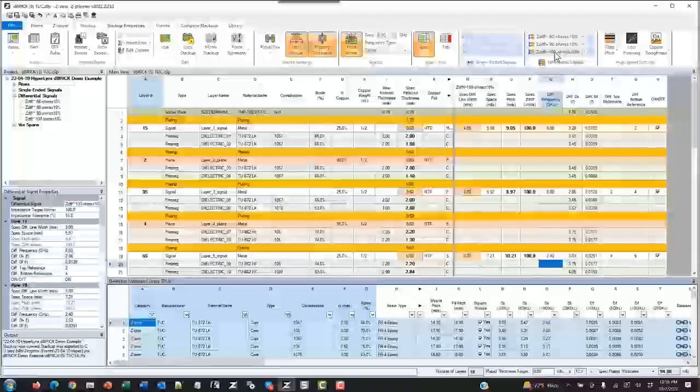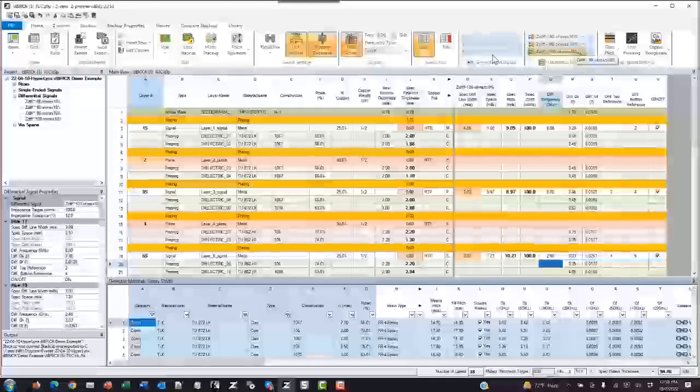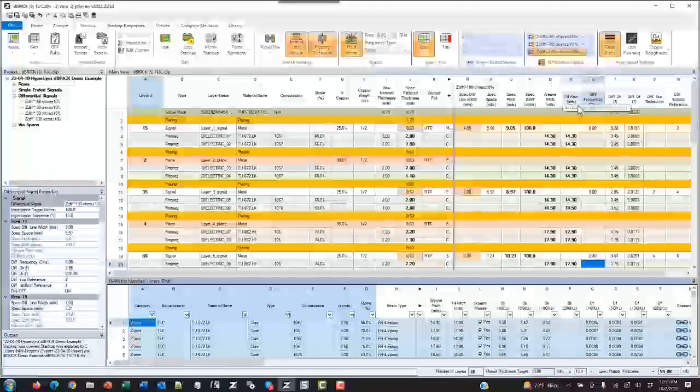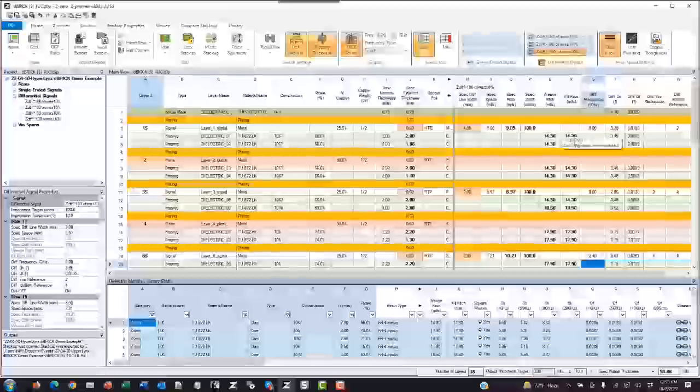100 ohms, looks good. I'm looking at a 100 ohm impedance group. There's several other impedance groups that I could look at in this design, both single-ended and differential. But we'll look at the 100 ohm signals initially. So I'm at 8 gigahertz. Recall that that was the frequency for PCI Express 4. And initially, I'm just going to turn on differential pitch fields, and it shows the weave pitch and the fill pitch. This is calculated from the type of glass that's used, and zPlanner knows all about the glass.